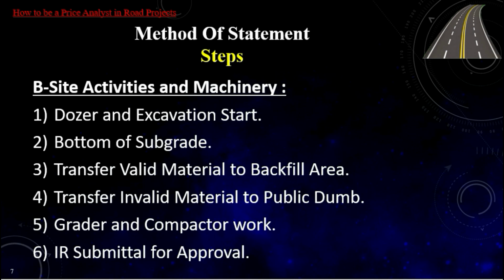The materials engineer from time to time follows up on the validity of the excavation product. The instructions must be clear and strict for the dozer operator to separate the valid materials away from the invalid ones. Since nobody can predict the percentage of valid to invalid material, the pricing engineer has to assume 50% for each, to be one of the obligatory risks of this type of item.